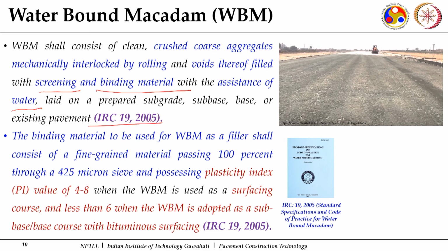And this is IRC 19, which gives the standard specifications and code of practice for waterbound macadam. Nowadays it is not very popular in the construction of flexible pavements. Instead of it, wet mix macadam, which we will discuss in the upcoming slides, is getting more popular because of a few challenges specifically related to its performance.